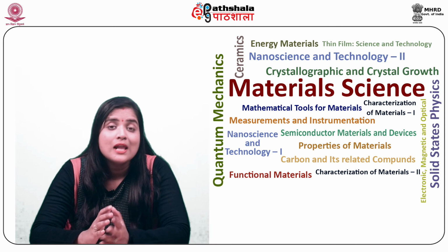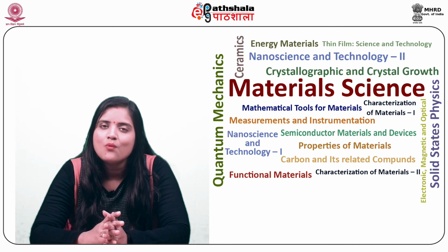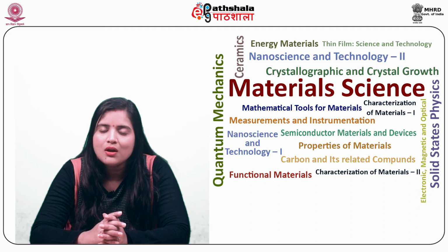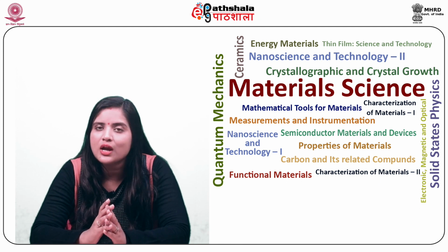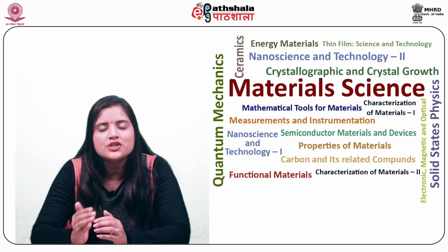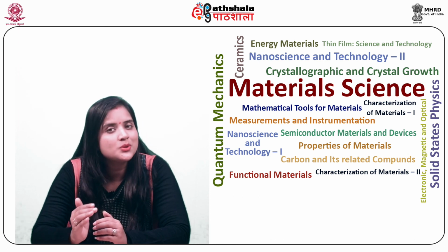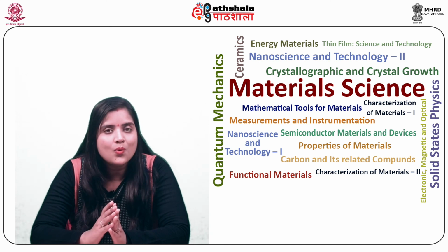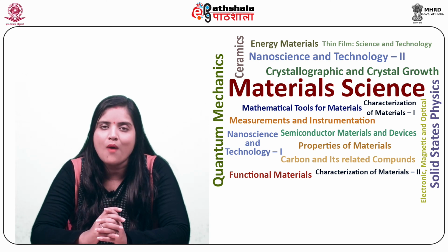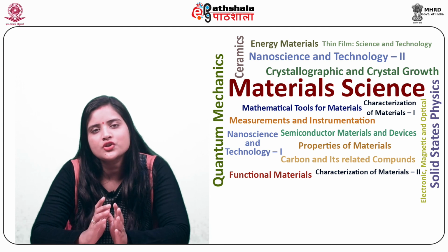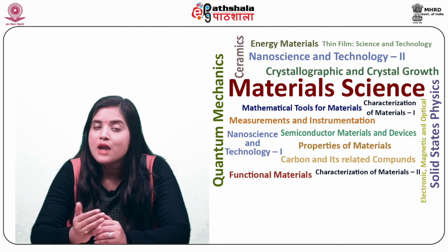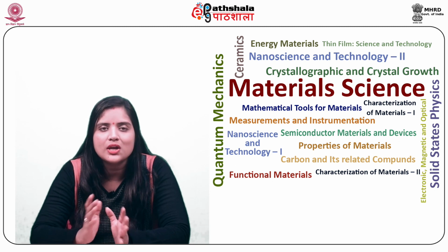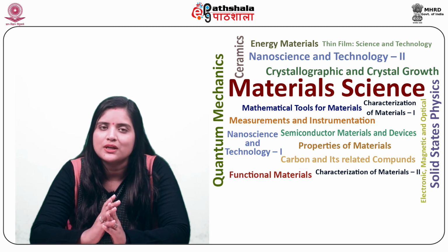So students, let us now summarize what we have learned in this module. In this module, the capacitance voltage characteristics of metal oxide semiconductor devices were discussed. Also, low frequency CV profile of MOS structure was studied and different regions obtained by sweeping the gate voltages were explained.